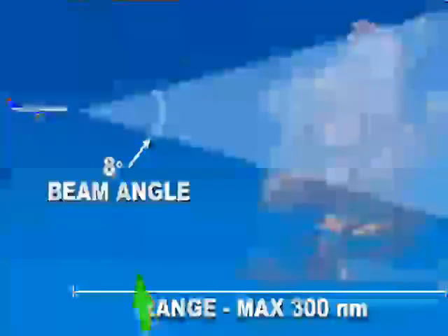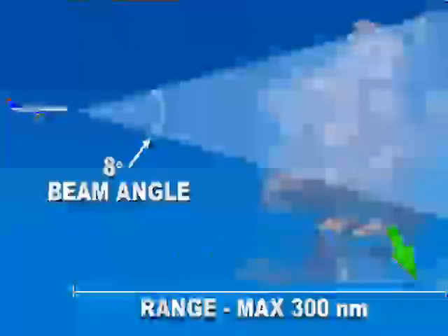Embraer jets are equipped with an X-band digital radar receiver transmitter and a flat plate antenna. The antenna's scanning angle is 120 degrees, 14 views per minute, or 60 degrees, 28 views per minute, and produces an 8-degree beam. Maximum display range is 300 nautical miles.